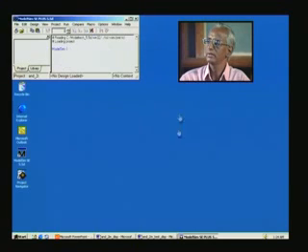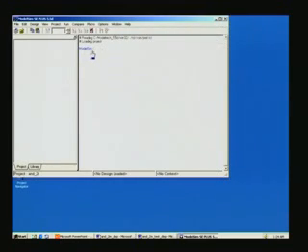So here that window is closed. Now you have this, may be difficult for you to read, and okay, I'll just enlarge this. Even then it will be very difficult for you to read. If you want to know what directory you are in, you can just say pwd in this command mode. This is a ModelSim prompt with the greater than symbol. This is just a prompt for the command. So if you say that one, note that we created and changed the directory to this. That is where we are now.